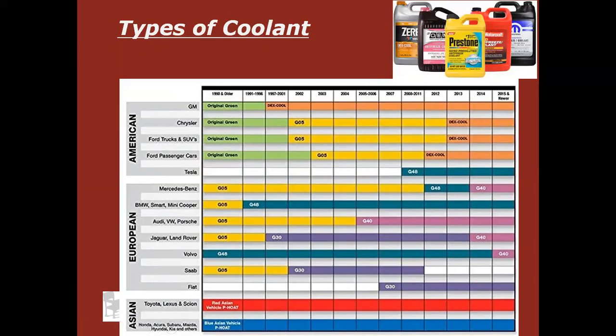So then companies discovered that, well, there's a lot of theories out there, and I'm not a coolant engineer, but you'll read that companies discovered that coolant could be tuned to whatever their engine type was, radiator type, that type of thing, depends on if the engine was an aluminum block or a cast iron block, different types of seals that are used in the cooling system and water pumps and things like that. And then the manufacturers started picking their own coolant formulations and saying that's only what will work in their vehicles. So that's where this chart comes in, and the craziness kind of began.